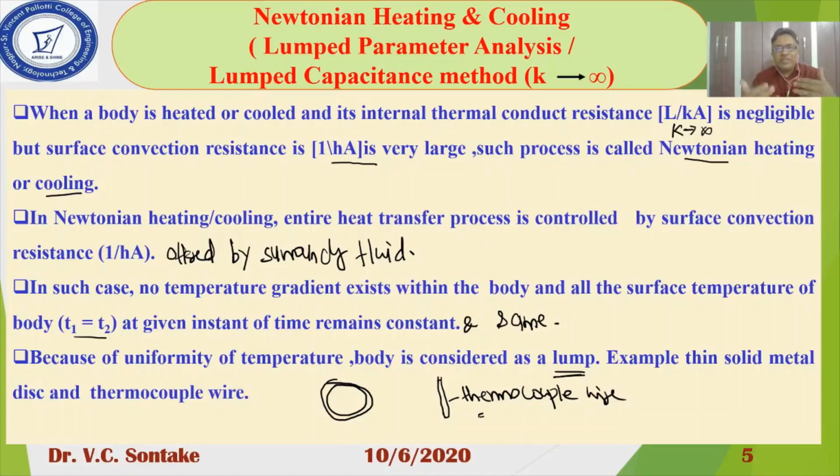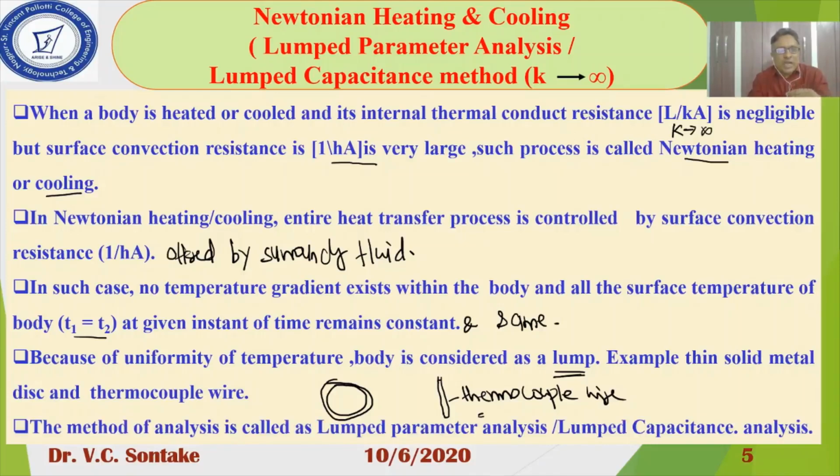The body is considered as a lump. Now, what do you mean by lump? I am going to explain in the subsequent slide. And the method of analysis is called lumped parameter analysis or lumped capacitance analysis. So when I analyze the temperature variation of such a body, whose temperature remains the same everywhere, that method is called lumped parameter analysis or lumped capacitance analysis.